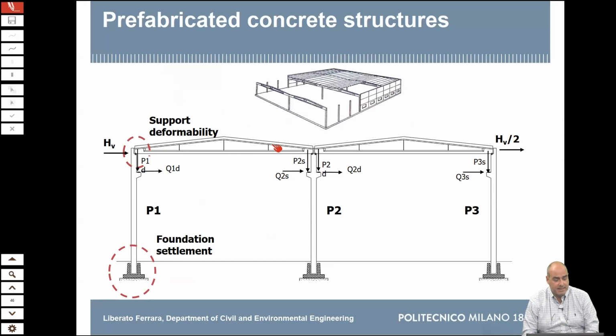You can see here, this is a typical precast frame. And you can have horizontal forces here, but these corbels that I'm pointing out with the arrow generally host a bridge crane. And the bridge crane transmits gravity forces, vertical forces, but because of eccentricity or because of the braking forces, it also transmits horizontal forces. And for these horizontal forces, you have to design the corbel, and the corbel is not a beam element in the sense of the Bernoulli theory. It has to be designed with a strut and tie mechanism.